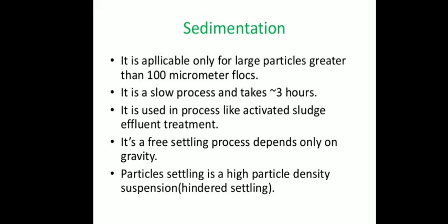Then the next type is sedimentation. Now the sedimentation process is carried out for the larger particles, having a size range of more than 100 micrometer.